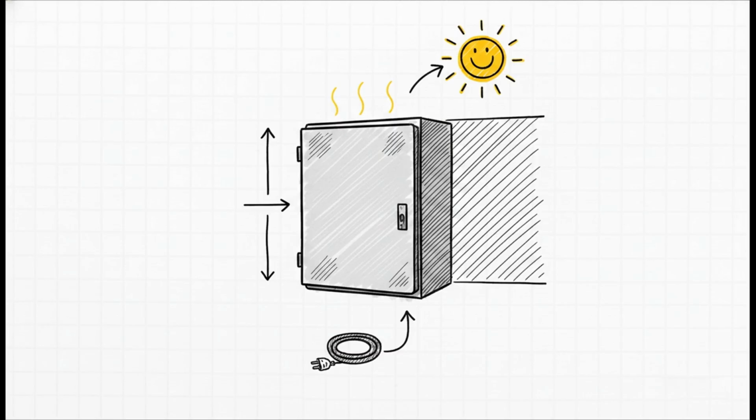For outdoor applications, solar loading can significantly increase the heat inside the enclosure. Even the color of the enclosure matters. A dark color enclosure in direct sunlight will absorb more heat than a lighter colored one. Power availability is also important. The tool needs to know what voltage and phase are available so it can recommend solutions that are practical for the installation.